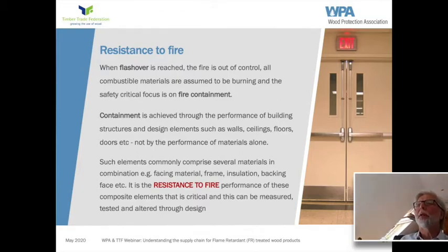So containment, building structures and design elements, gives a fire resistance performance. And as I say, that can be measured, and it's normally expressed in minutes of resistance to fire. So we talk about a fire door being 30 or 60-minute fire resistant.